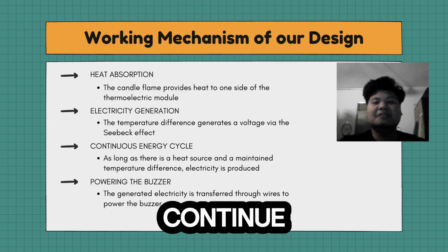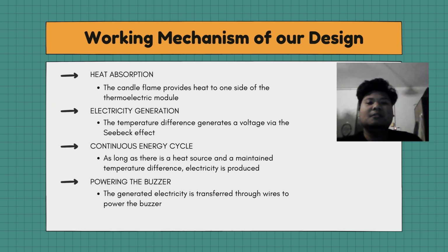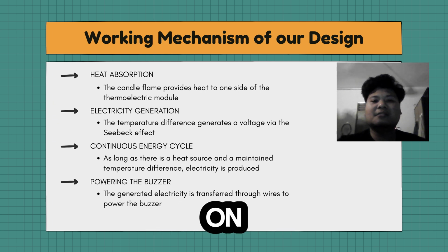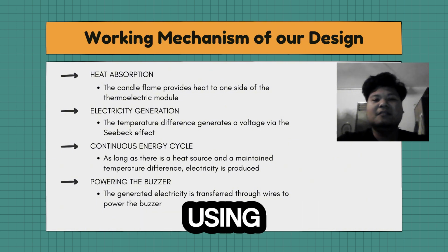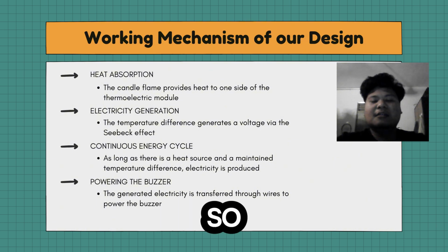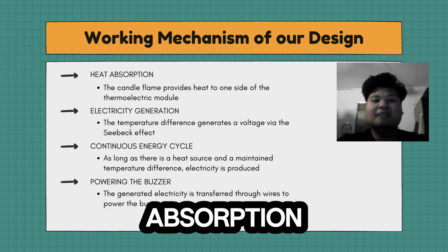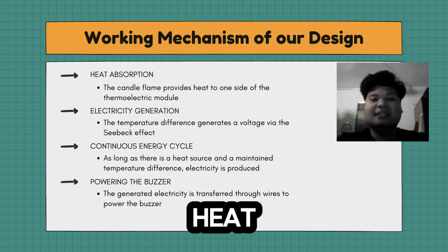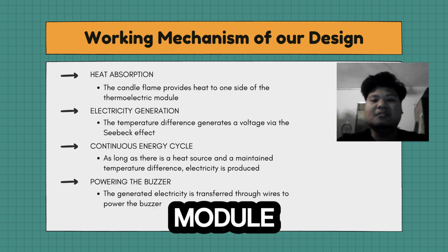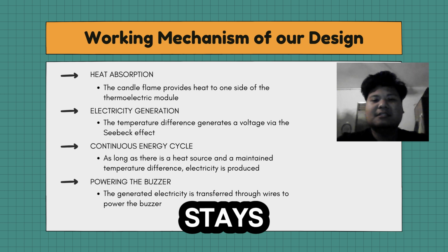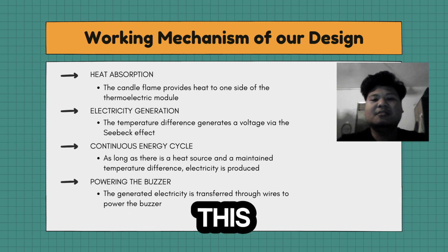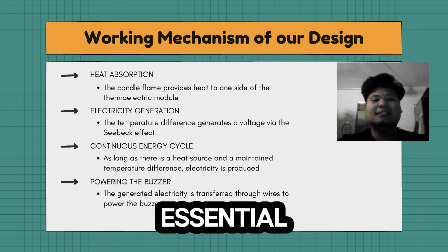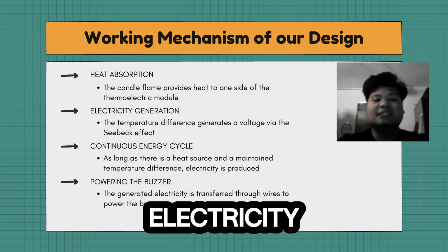Next, let's continue with our working mechanism. So, our design operates based on the thermoelectric principle, transforming heat into electricity using a temperature difference. So, the first one, heat absorption. When the candle is lit, it transfers heat to one side of the thermoelectric module, while the other one stays cooler due to the surrounding air. So this temperature difference is essential for generating our electricity.